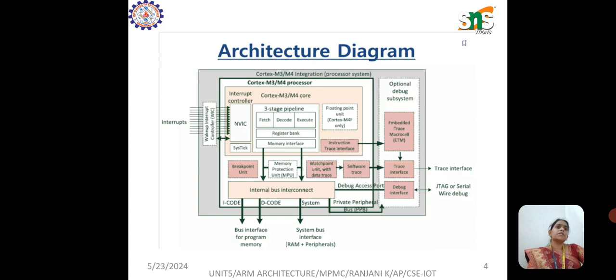Both multiplier factors are 32-bit inputs, and the inputs are returned from a register file. And you have a barrel shifter. The barrel shifter features a 32-bit input to be shifted, and this input is coming back from the register file. Next you have a control unit, and the control unit is sometimes a pure combinational circuit design. It is implemented by state machines, and the process timing is included within the control unit.